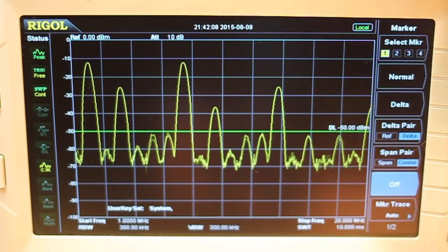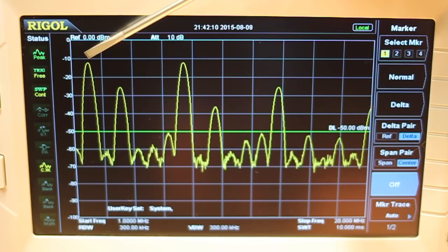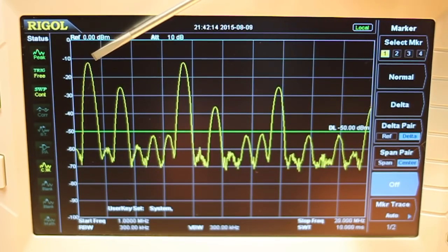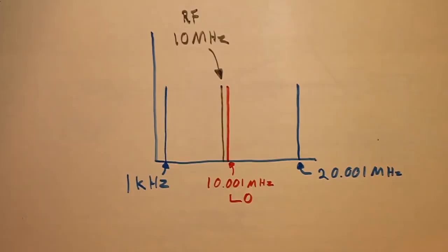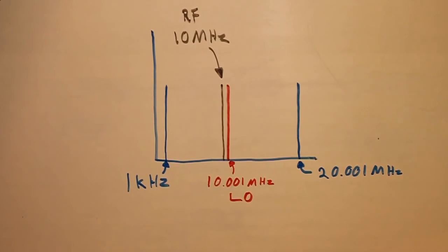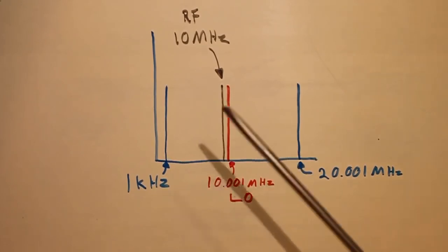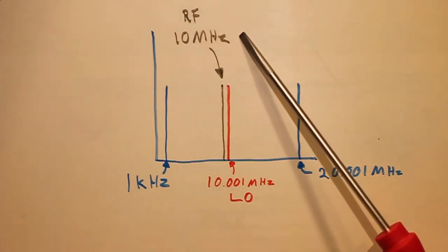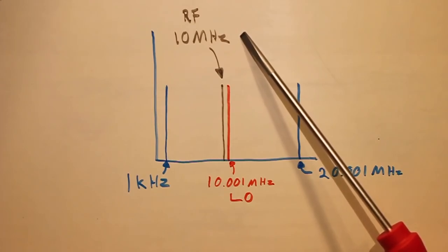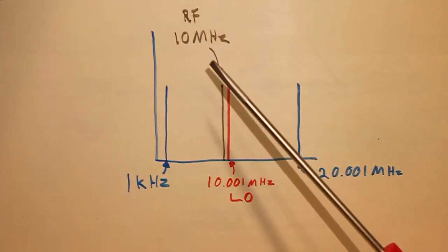For example, if we were only interested in the difference frequency here at 2 megahertz, we'd just stick a low-pass filter on the output of the mixer, and that would knock out all of this higher frequency content. And what this is used for is frequency conversion. So let's say that you're transmitting a signal at 10 megahertz. And let's say it's just a steady carrier wave. You're not modulating it at all. It's just a steady tone, if you will, at 10 megahertz.